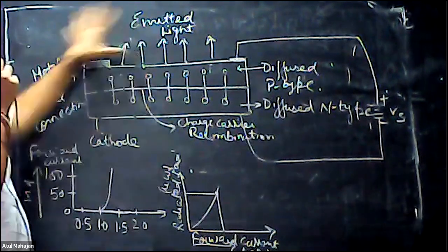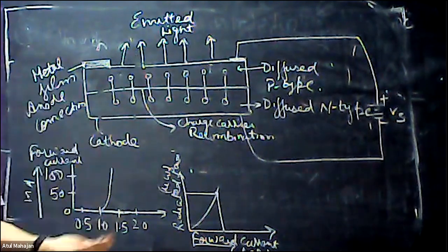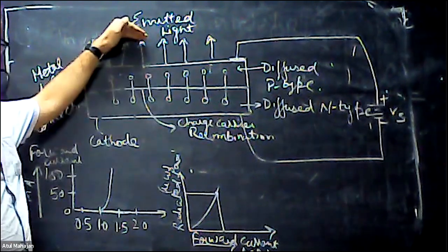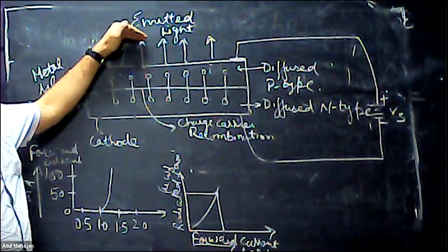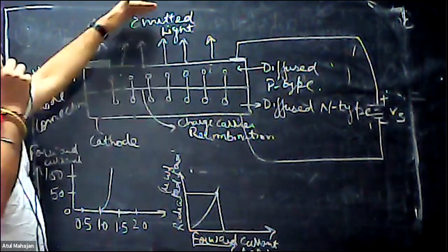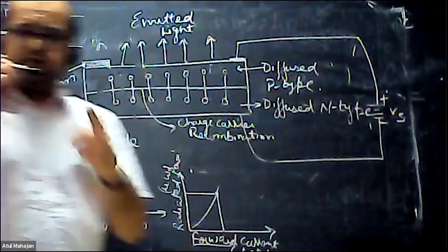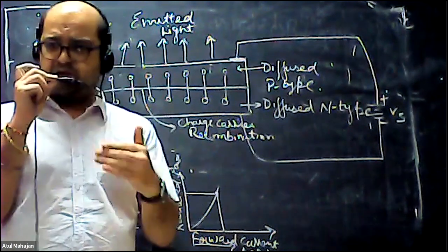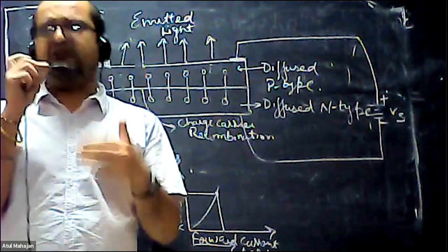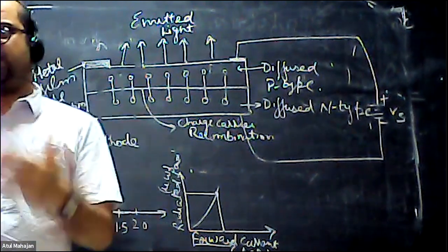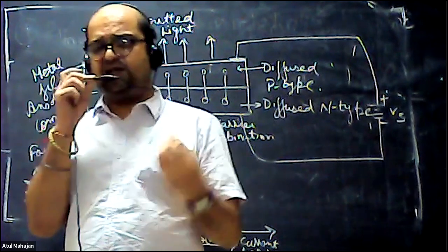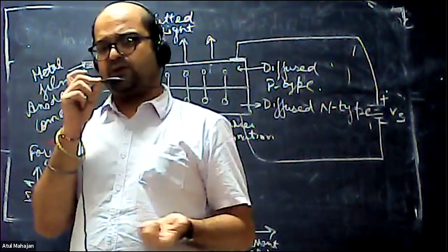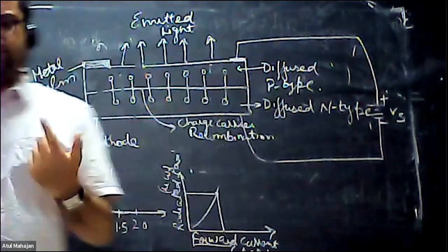So this is actually the recombination process. Whenever we apply the forward bias voltage, the recombination process starts and emits energy in the form of light, a bundle of energy, a quantum of light, whose particles are known as photons. Along with the light, they also emit heat energy. That is why, if LEDs keep glowing for a long span of time, they get heated up when you touch them. So heat is a byproduct of light emission.